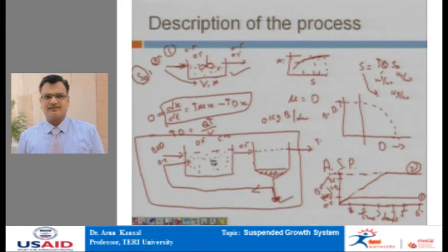That is why it is known as the activated sludge process, which consists of an aeration tank where a very high concentration of bacterial biomass is suspended and they are artificially increased by recirculating part of the settled sludge back into the system. So this is broadly the functioning of the activated sludge process. Always remember, when we say activated sludge process, it consists of an aeration tank followed by a secondary settling tank and a sludge recycling line and sludge wasting line, and a treated water effluent line. This entire system, aeration tank, sludge recycling line and secondary settling tank, together is called the activated sludge process.